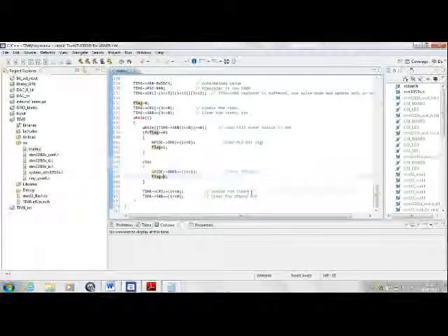Next, remember I'm using the timer in the one pulse mode, and in one pulse mode the counter enable bit becomes 0 after an overflow has occurred. That is why I restart the timer by setting the enable bit, and the status register is also cleared. Else, as soon as you execute this code, you'll come back here and this time the while loop will not work and it will not wait till the counter has counted 1 second.